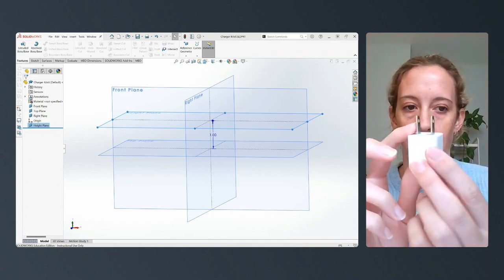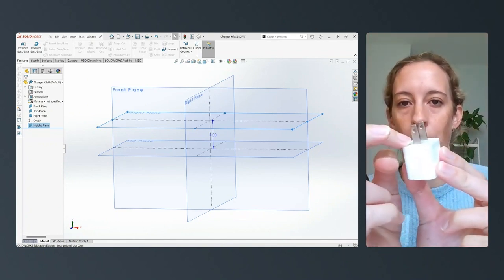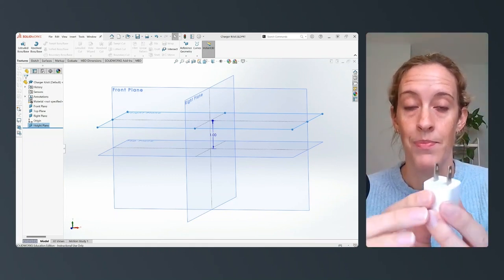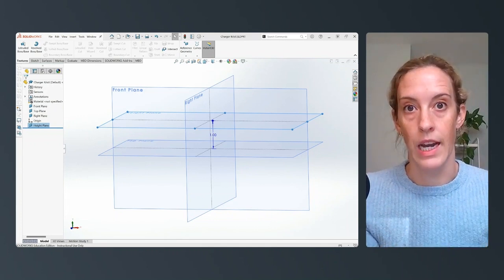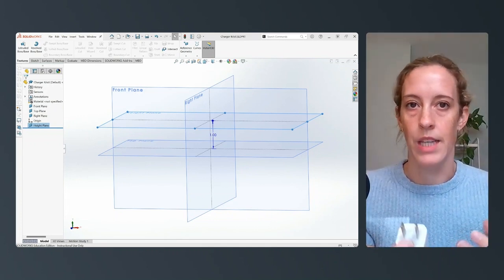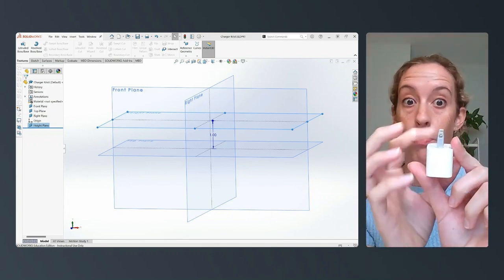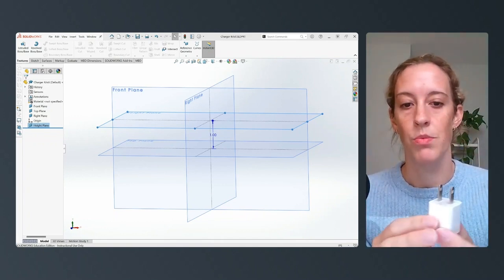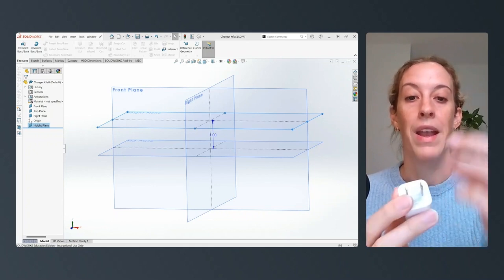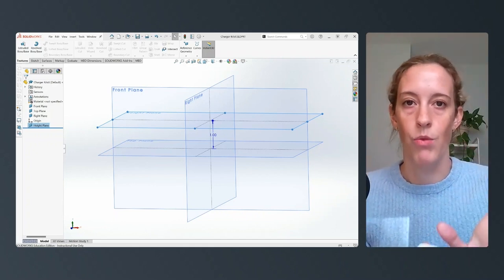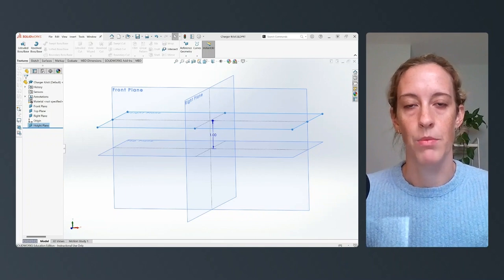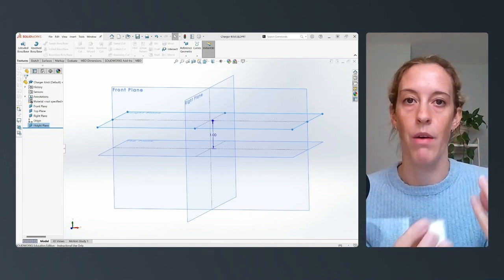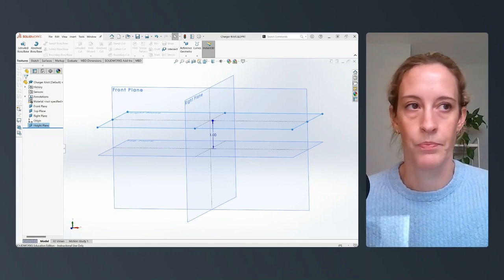For example, imagine if we modeled this whole metal part and then we just modeled the same metal part again, that would be a huge waste of our time, especially if we were creating a new design and let's say later our team decided to change something about both of the metal parts, then we would have to do that whole change twice. So it's much smarter if we can just model one half of a symmetrical object and then we can mirror it across that plane of symmetry and avoid duplicating our work, because we can always go back and edit one side and that would propagate forward to the mirrored side.